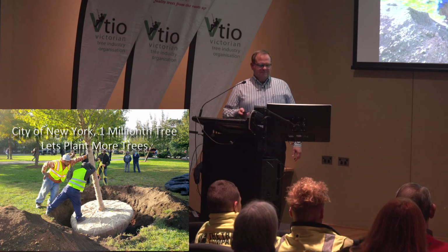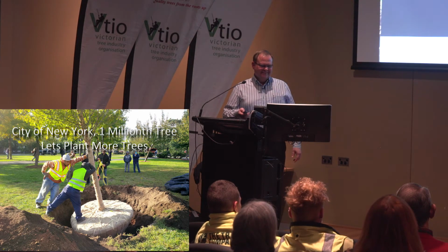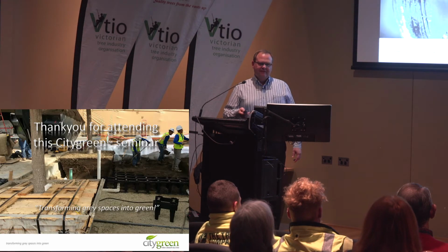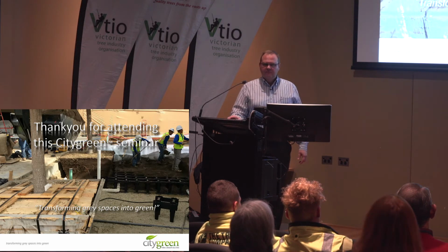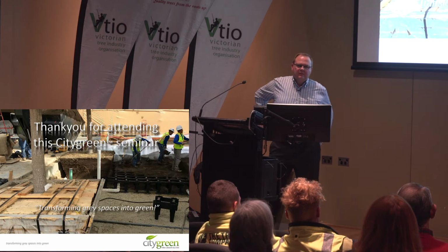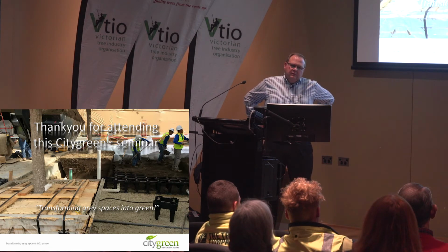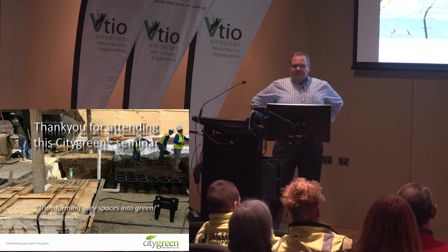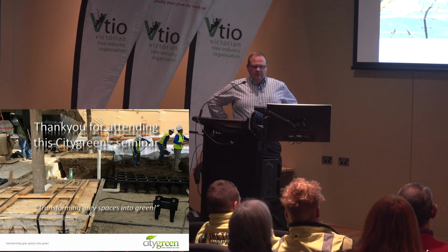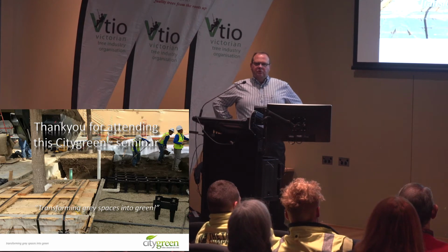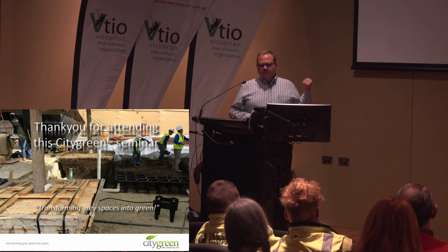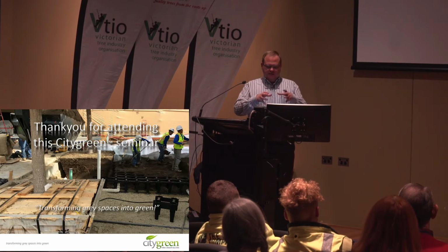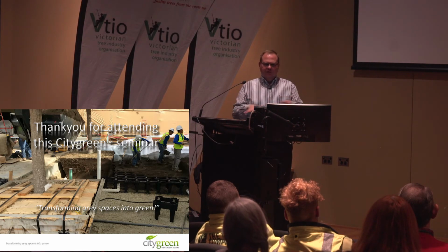So, any questions? Yes? One of the questions that I've been asked when proposing your structural cell system is, do you need to pull up the entire infrastructure when it's time to remove the trees? Yeah, that question does come up a bit. No, you do not. Essentially what you do comes back to correct design. Talking about the Bartlett trial, that was bad design. They just sat a tree hard on top of the cells, so those roots are just tangled up with the cells.